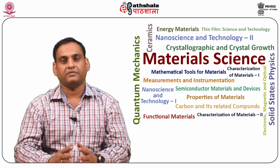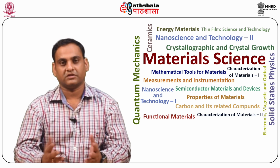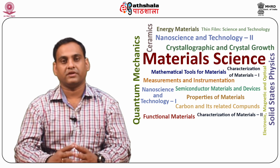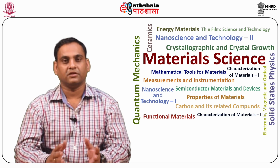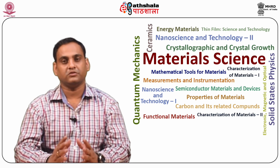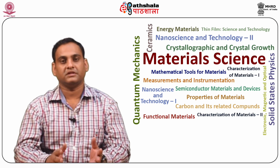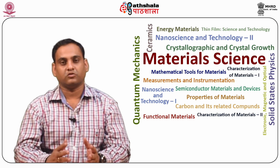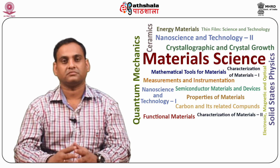This is achieved by various hot and cold rolling stages to produce textured sheets known as grain-oriented silicon steel, with the 001 direction in the length of the lamination. The 001 type crystal directions are the easy direction of magnetization, and hence the permeability is greater. The anisotropy of iron can achieve two types of textures, which are known as cube on edge and cube texture.